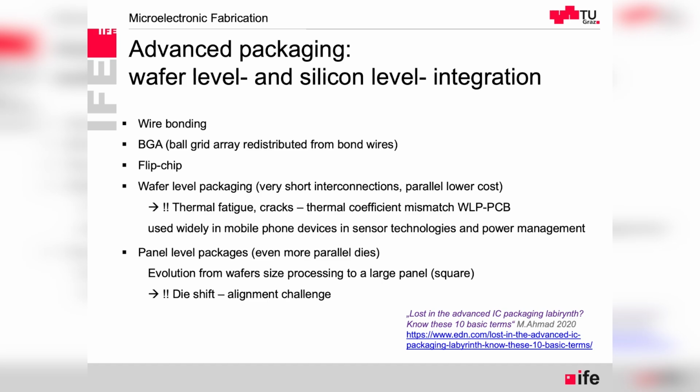And so in summary, what we see is the wire bonding, ball grid array with, most of the time, the flip chip. And in terms of packaging, I don't have a good picture, but at least I have an added link where you can also learn about it. What we have to know is that some applications need large areas of silicon. There are different ways to consider it. You can slice it and then make packaging side by side for the large application of, for example, panel detectors.